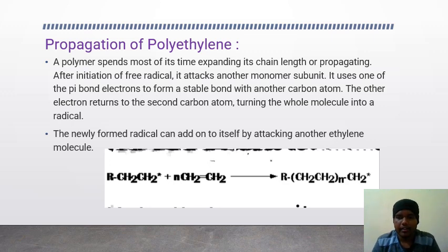Propagating in the context of polyethylene also refers to the process by which a crack or fracture can propagate through the material. Polyethylene is a type of polymer, which is long chain molecules made up of repeating units called monomers. The properties of polyethylene, including its ability to resist propagation of cracks, are largely determined by the molecular structure of the polymer chain. The propagation of cracks in polyethylene can be influenced by several factors, including the properties of the polymer itself, the environmental condition, and the presence of other material or contaminants. For example, the presence of certain chemicals or solvents can weaken the bond between the polymer chains and make it more susceptible to cracking and propagation.